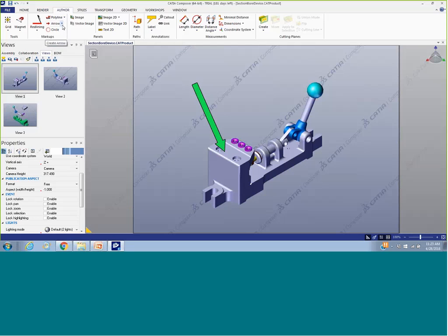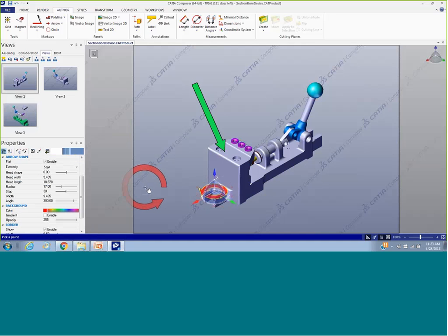Now again, there are some other types of arrows you can create. There's a circular arrow that you can do as well. With the circular arrow, you basically align it with a face, and once you've got it on the face, get the right distance up and down, and now it makes the circular arrow. Once you've got it created, I'm going to escape to stop building that. Again, you can now come back here and modify your properties.